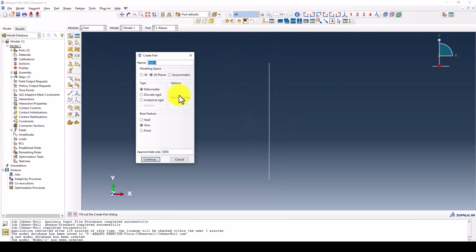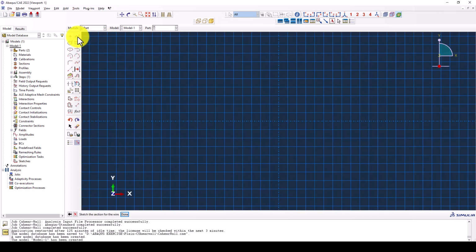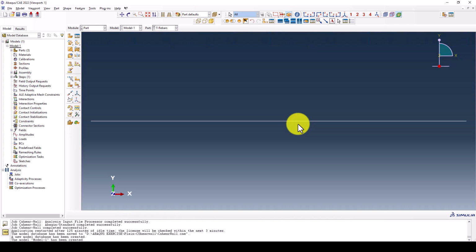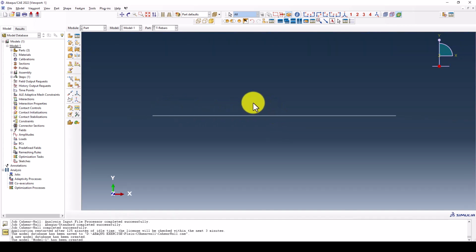The horizontal one is equal to the width of the shear wall, and I'm going to call it transfer rebar. The same method, and the size is 1400, from 0, 0 to 1400, 0. In the foundation we do not have vertical rebar. You can add it in case you want to verify or simulate an experimental work.